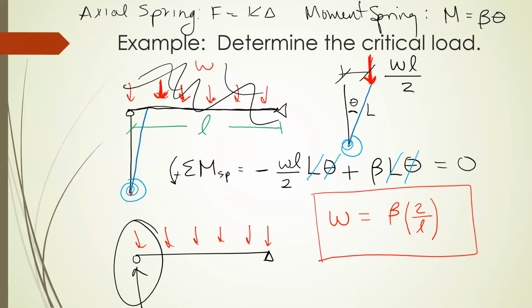So did the length of the column change when it rotates? No. The length of the column is now inclined. That stays the same. Over here, this vertical dimension, technically it's less than L, but if we're dealing with a small angle, L times the cosine of theta is equivalent to L. So it's approximately L. But if this starts to become nonlinear and the column starts to lean more and more, at some point you can no longer approximate that height as L.